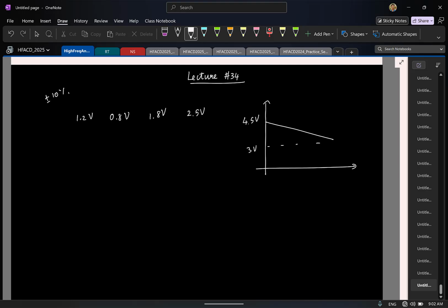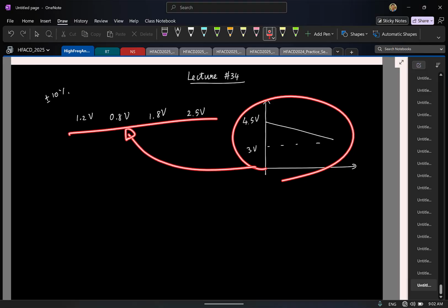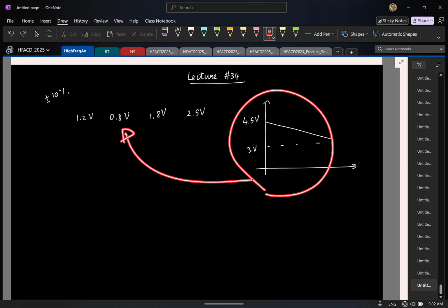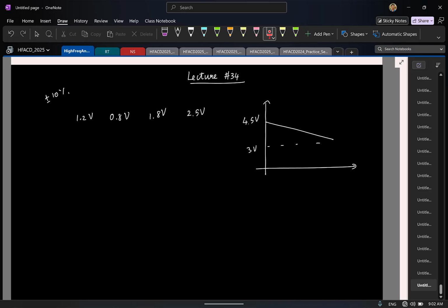Right? So which means if you directly rely on your battery voltage to generate all these supplies, that is not a great use, because the discharge range is so much and you can tolerate only 10% change. You can't tell the customer that your electronic system will work only if it's 100% charged.